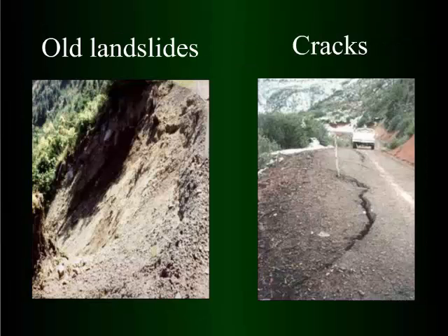Another example of a landslide. This is an example of a tension crack that says that piece is moving and that there's a reason for it. We need to find that out and fix it before we lose the road. But you can see that tension crack, it runs a pretty good size area. Whoever gets to fix this is going to be out some money.